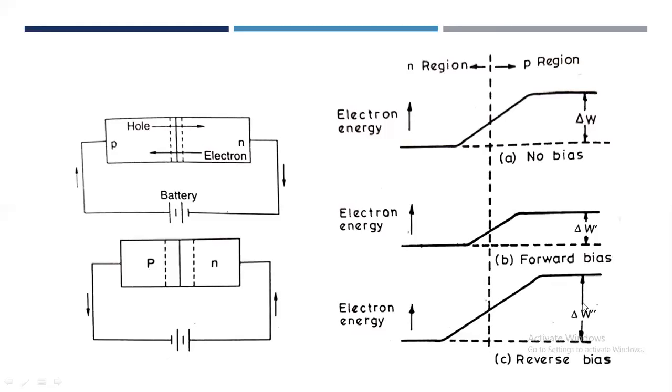As noted earlier, the small current in the reverse bias mode is due to the thermally generated minority carriers, which are always present in each region, and which of course transfer across the junction region. At higher voltage in the reverse bias, breakdown sets in. Suppose a very high voltage is applied in the reverse bias mode, then the junction may break, that is nothing but breakdown sets in.